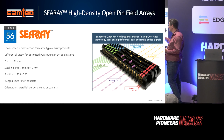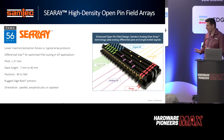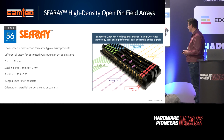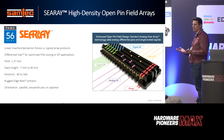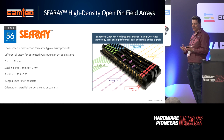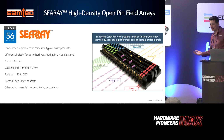But we also have many customers asking if you can do single-ended RF over that kind of connectors. And the answer is yes. So if you're looking, for example, on a connection where you have 10, 14 SMP connectors for a board-to-board connection, you can do that with an array product. And it will save you a lot of space on your board, and it will save you a lot of cost. Because traditional RF connectors, they are machine-based, so it takes a higher cost than building a stamp and form contact into a molded plastic, basically. So it's just the manufacturing cost of the different device.